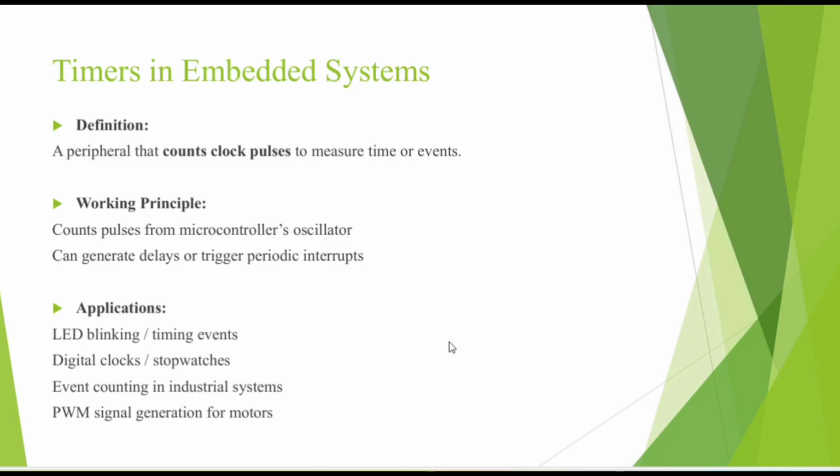Then, in the next slide, we will see the timers in embedded systems. Timers in embedded systems are like your phone's alarm. They help to manage time-based tasks. First of all, what are timers? A hardware counter that triggers an event or interrupt, used for delay, PWM, frequency measurement, and so on.